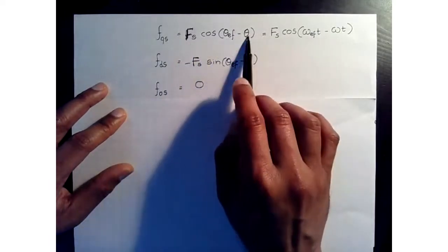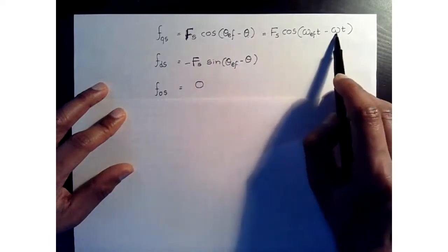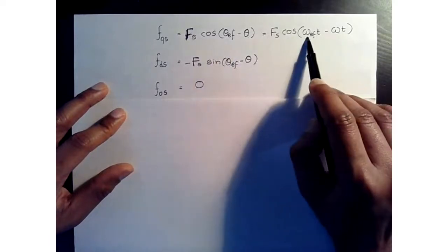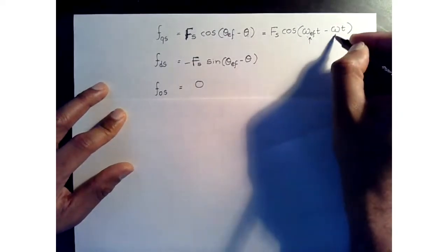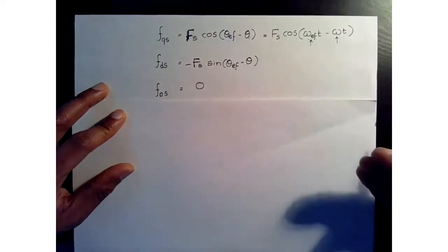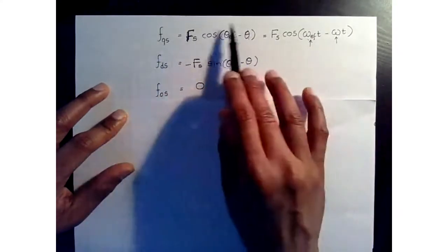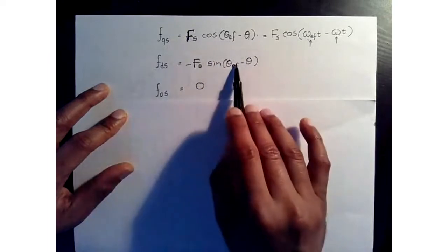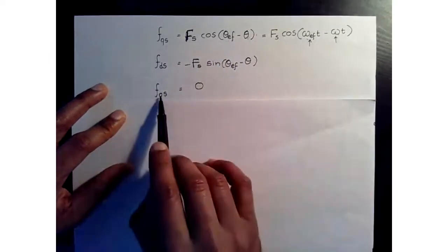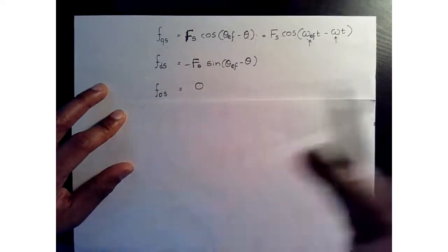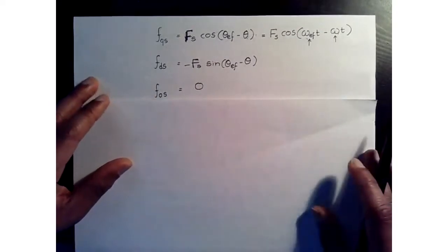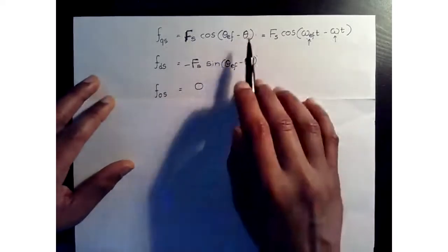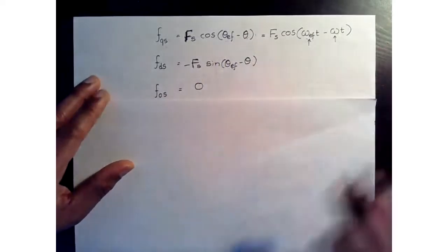These two theta positions are different because for now we are only considering a signal with two different frequencies. This is the signal frequency. This is the frequency of the frame that we are looking at it from. Then for QS, it has a cosine nature. DS has a sine nature, with a negative sign here, and then we also have our zero sequence, which is 0. This is under this balanced condition, and we are rotating at this omega frequency.